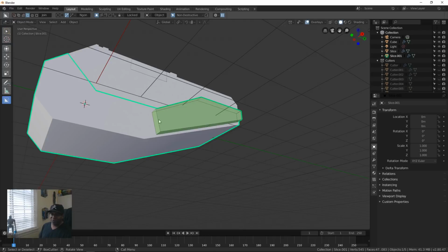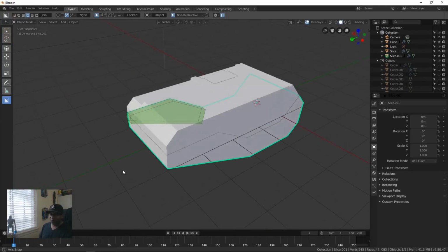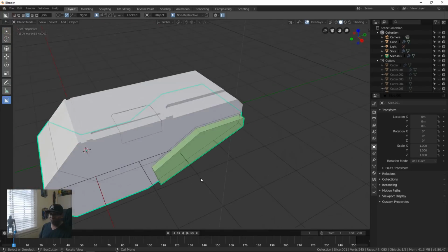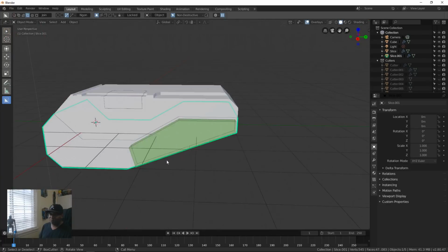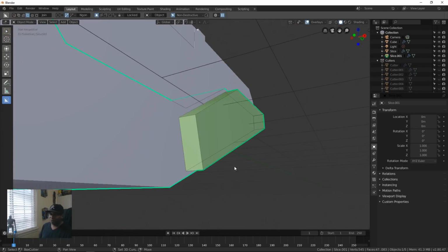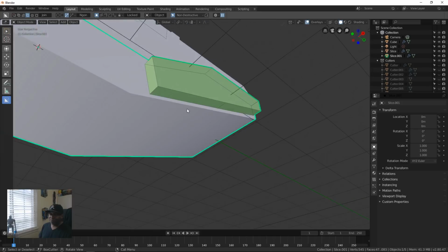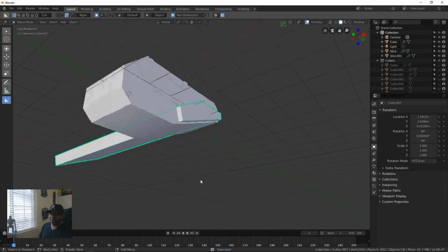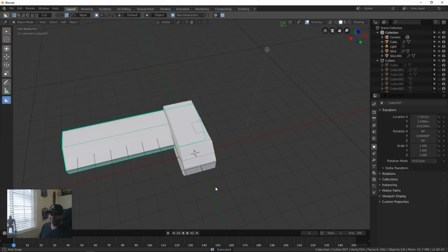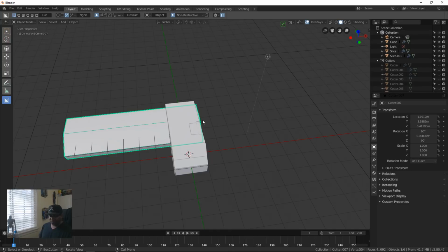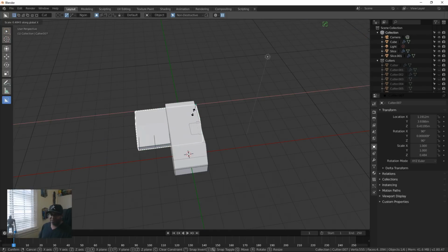I'm just going to put this on here, and since we're really just working on one side, I'm going to show you how you can pull some symmetry off the other side. So anyway, green box, right? Green box is going to be a live object. I'm going to hold shift, click it, and it goes through to the other side. Now I need to scale this, so I'm going to hit S, X, bring this back in, and I only want half the distance because I'm going to mirror it.